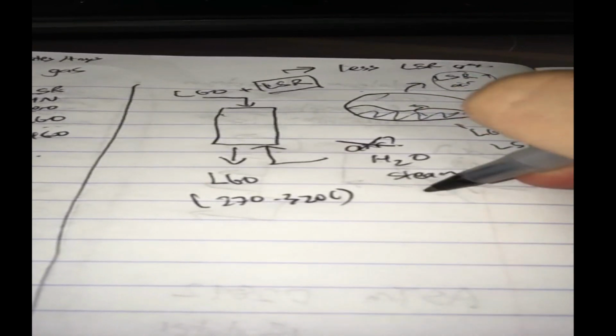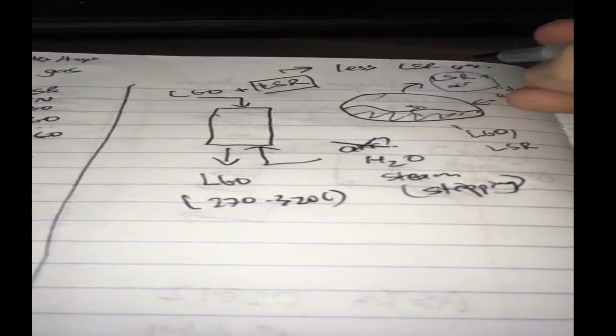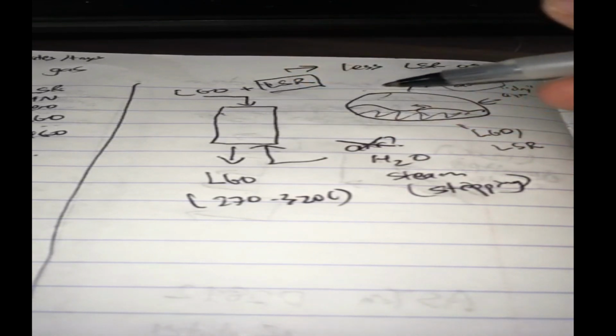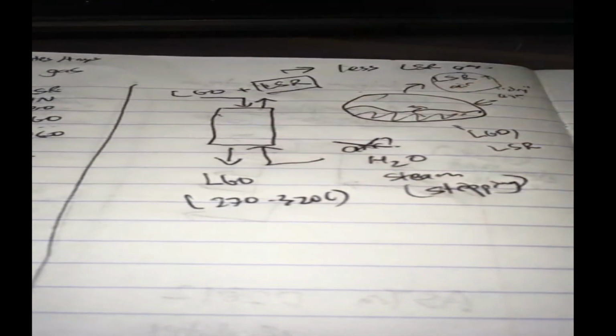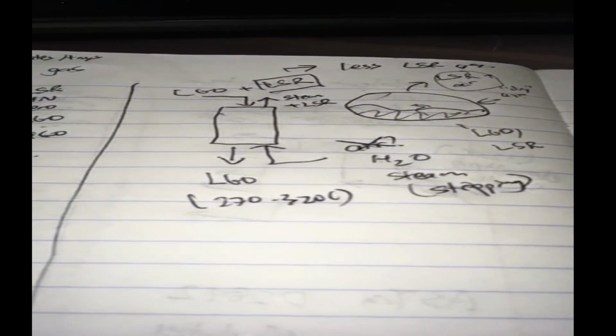Safer alternative and very practical. Use water or steam. In a refinery, they call this stripping steam. So stripping steam will again be like the air, except now that you're not trying to evaporate water vapor, you're trying to evaporate all the light straight run gasoline and everything else out from your light gas oil. Well, it's a safer system. Alright, so what comes out, you have steam plus LSR, like straight run gasoline, not naphtha.